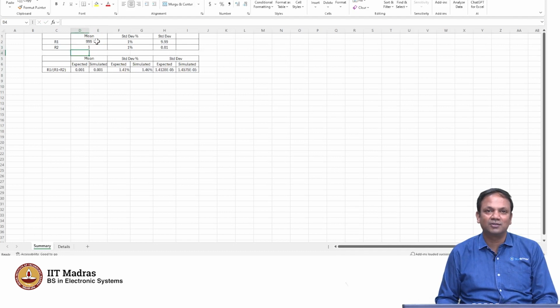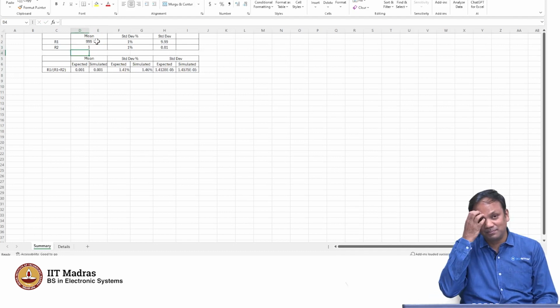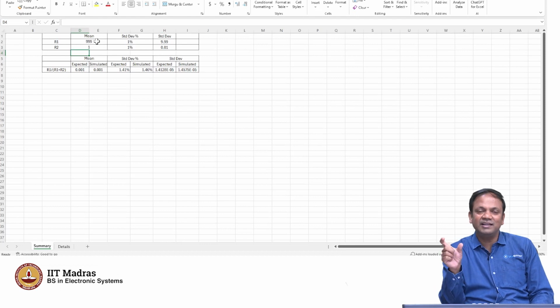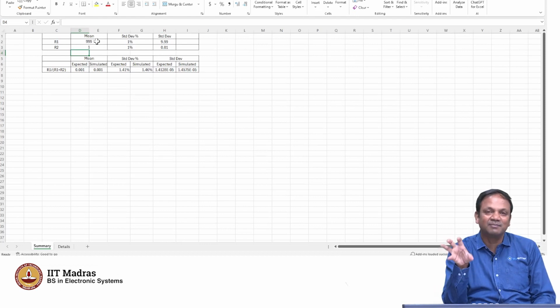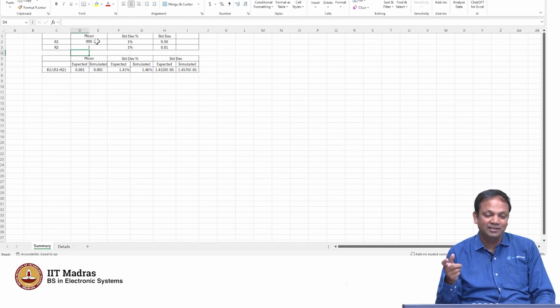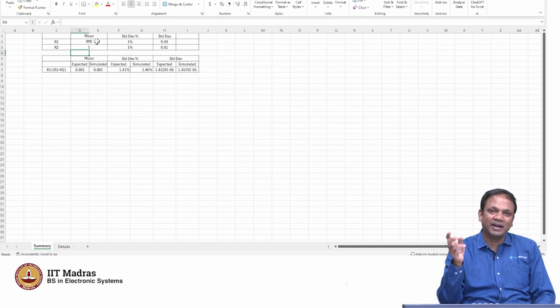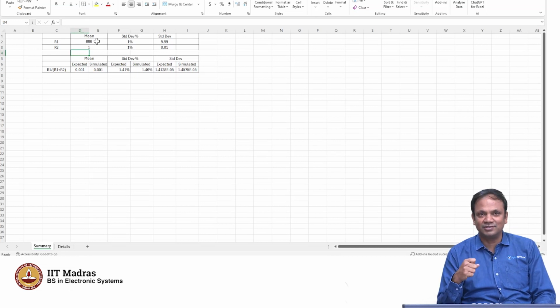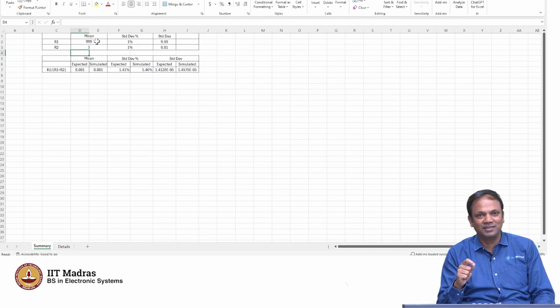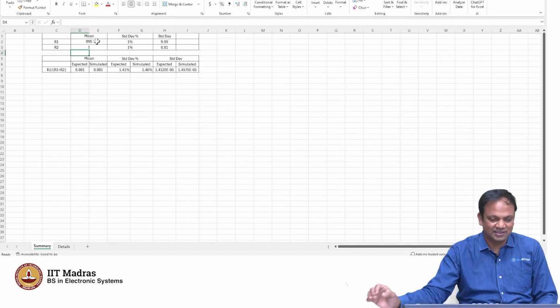R2 by R1 plus R2 is actually just R2 by R1, right? At least when the resistive divider was a ratio of half, when the two resistors were equal, any variation was getting compensated by the other component. Whereas in this case, it is practically just R2 by R1, where you would think that now the standard deviation should be higher, because R2 can move in one direction, R1 can move in another direction, and there is no compensating effect.